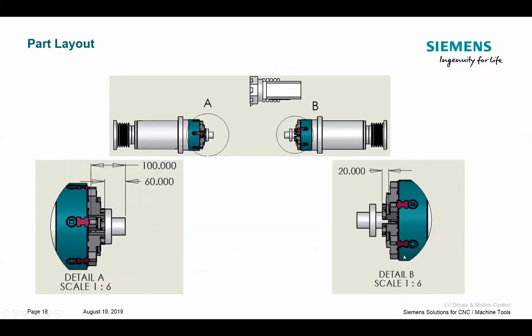So we're starting to move forward a little bit. We start to think about what we want our part to kind of look like, where we want it to nest. It's important to think about not only the finished overall dimension of the part, but what the rough stock of the part length is as well. Because you're going to be taking off that dimensional data, you'll be clearing off some kind of facing material probably from both the first operation on the main spindle and the second op on the counter spindle. So we want to anticipate and think about that when we're going and grabbing.